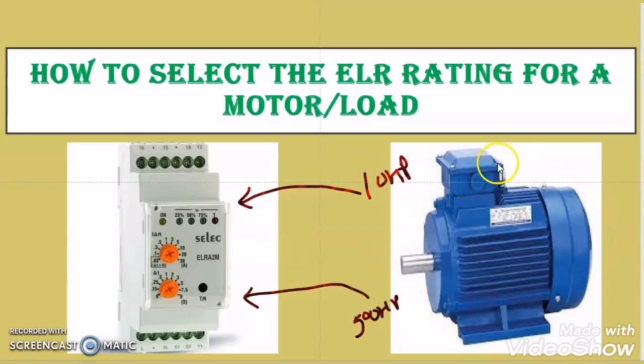For protecting the equipment from the earth fault, there is already one type of relay available, that is the earth fault relay. So hope you understood till here that the purpose of earth leakage relay is not to protect the equipment, but to protect the human. But while protecting the human, the earth leakage relay is protecting the equipment also. Let me elaborate this one to avoid this confusion.